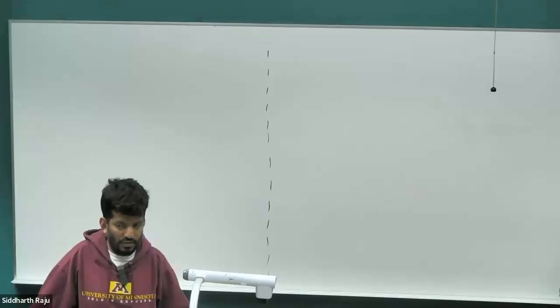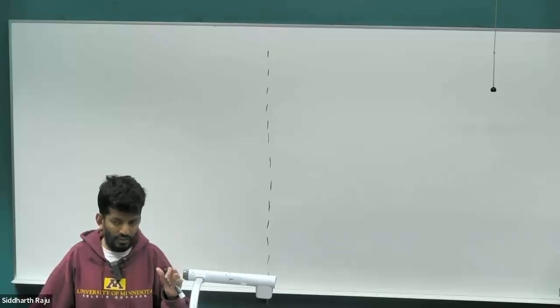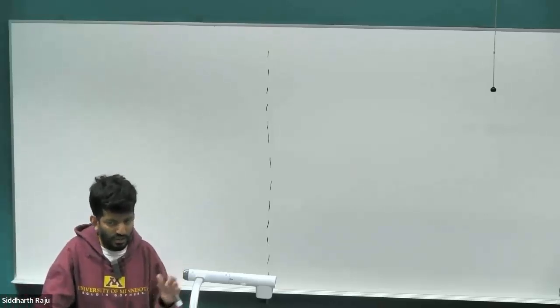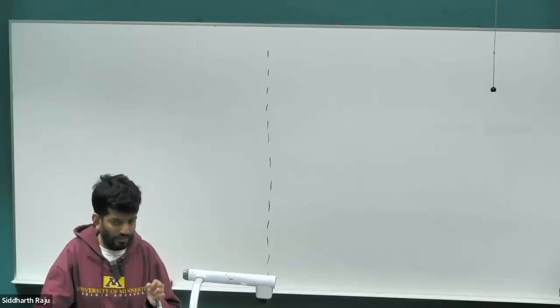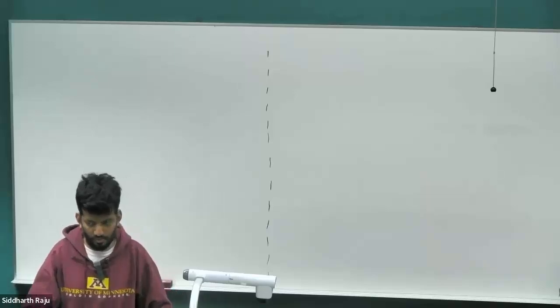The first one is addressing one of the commonly occurring confusions for people when they work with permanent magnet synchronous motors, which is the three different terminologies that I used. One is the torque angle, the other one is the load angle, the third one is the power angle. These three terms mean different things, and there's quite a bit of confusion between what those terms mean because different textbooks address different ones of these angles without providing too much of a complete context to it. And that caused a little bit of confusion about what the terms mean, which point is stable, which point is unstable, and so on and so forth.